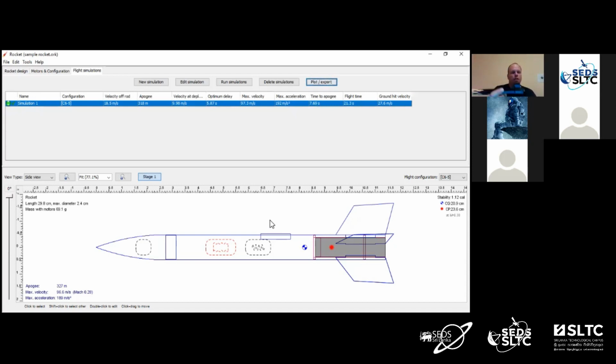So here's how this works with a small rocket. This is for black powder motors only. This doesn't work with the ammonium perchlorate composite motors that we talked about. But for black powder, they're easy enough to ignite that this will work with a very simple setup. We can have what we call a coupler.